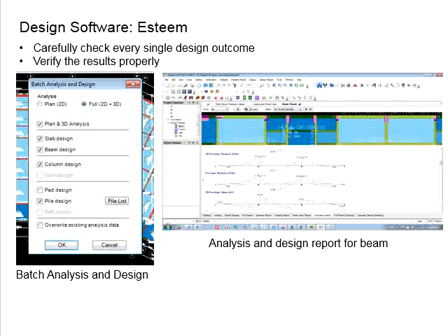Also, when you check the design, you need to look into the parameters being used. Did you key in the right design parameters, or overlook something during the input stage? This is a means to cross-check that you have keyed in the input correctly. And you can also make relative comparisons among different members by observing the loads acting onto the members in terms of shear and moment, relative to the other members in terms of the amount of reinforcement bar or the size of the members, to see if there are any logical correlations.